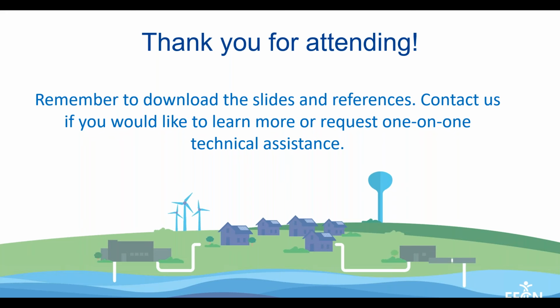I would say extended aeration is probably preferable from an operator standpoint because every move is not so critical. Because you know the solids are in there for 20 to 30 days and the aeration time is 18 to 36 hours. You have a little more flexibility to make adjustments and not end up with major problems.